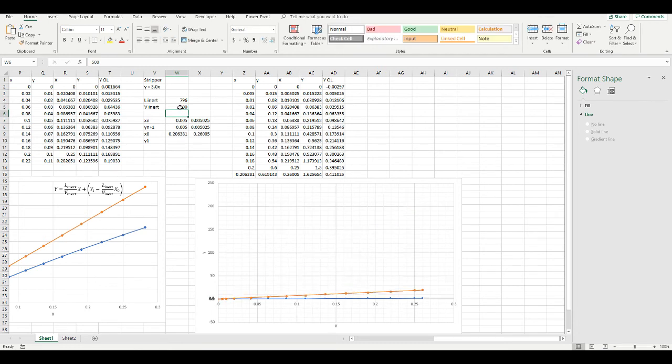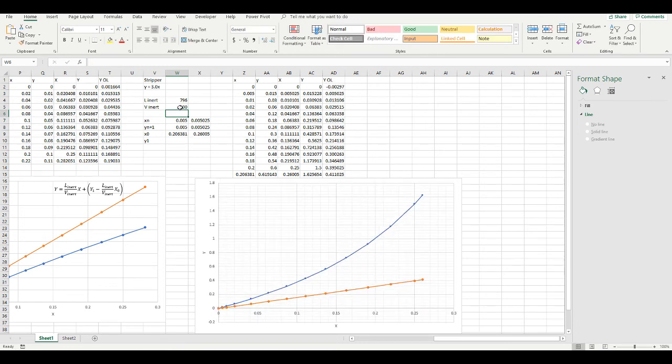So let's say we pick 500. You can see that this changes the slope of the operating line. And so we need to adjust this until we find one that gives us 4 stages. So let's start with 1000 as an arbitrary value.